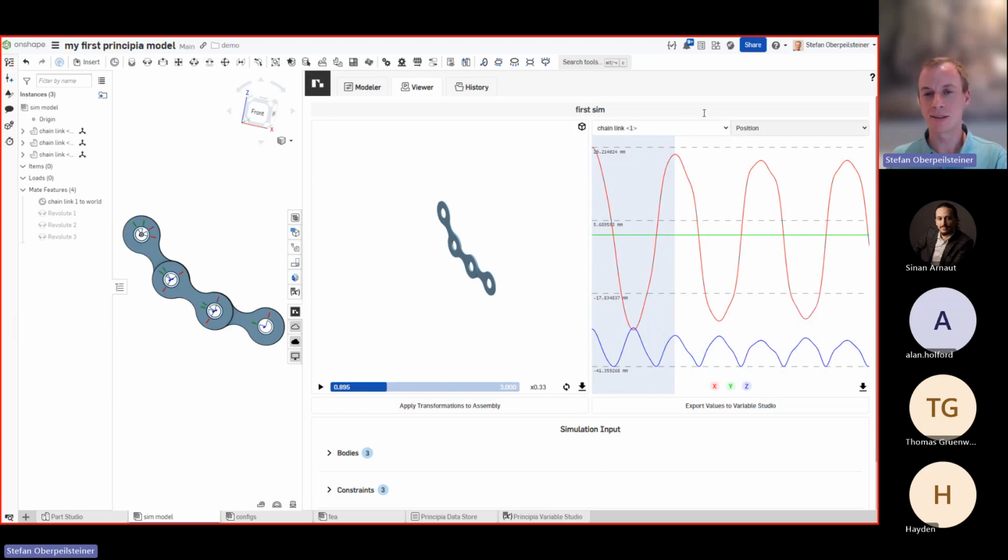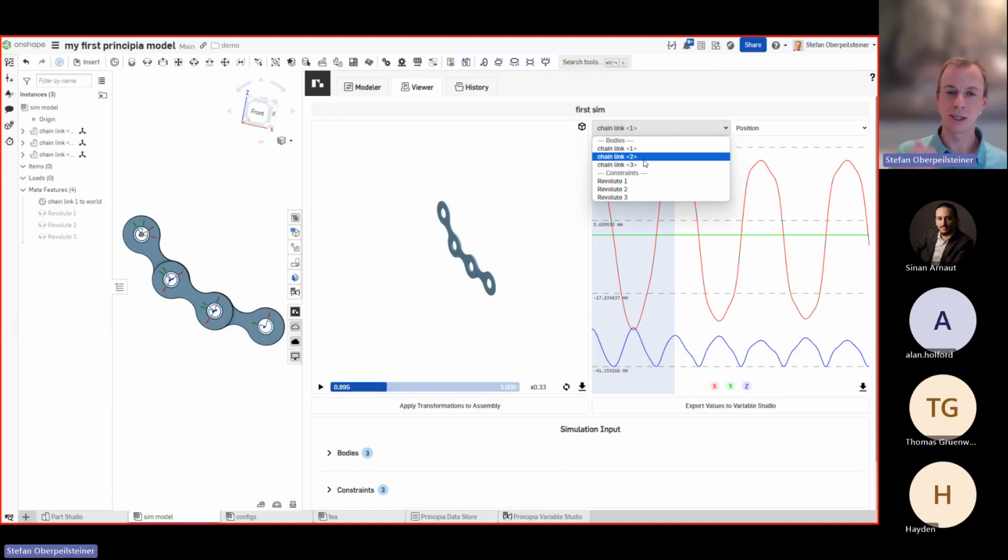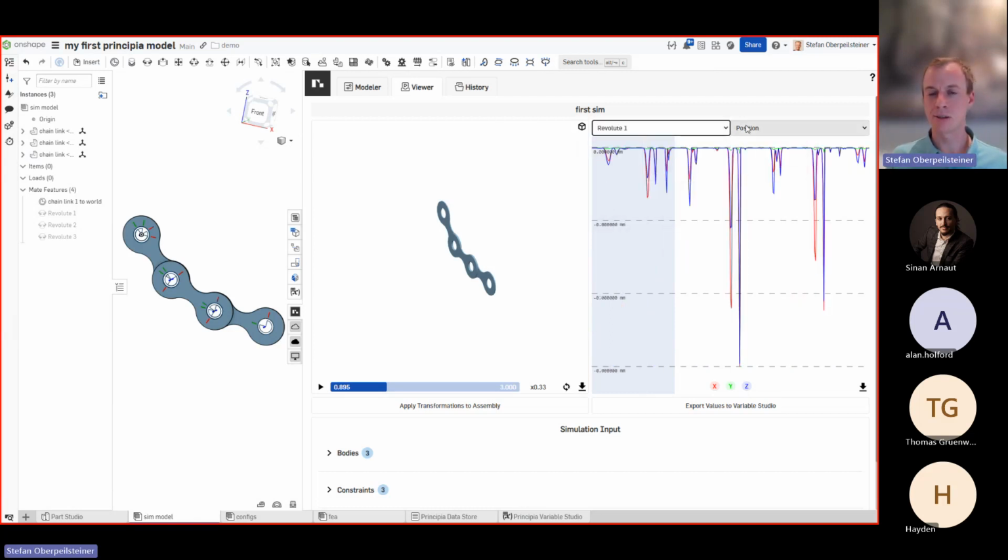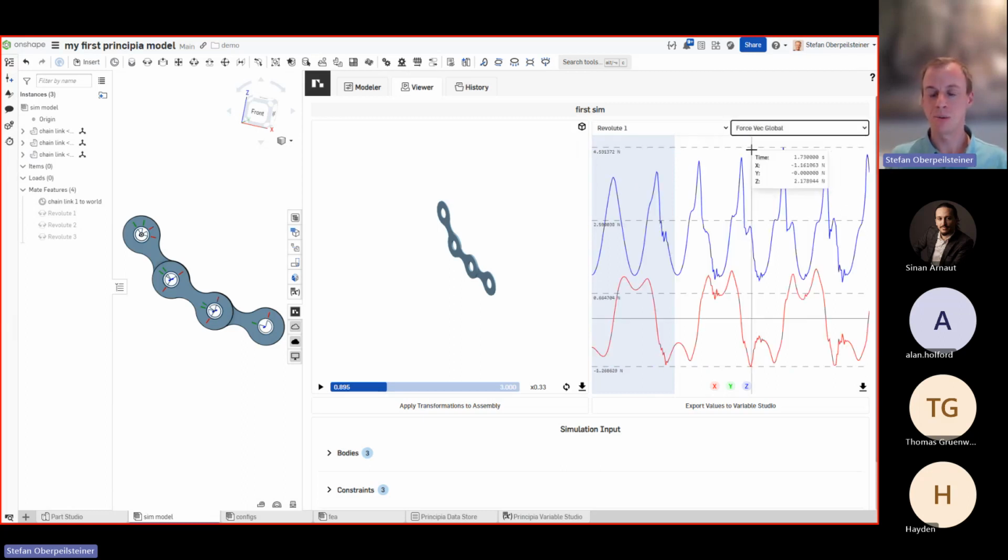On the right-hand side, you see the XY plot. And in the XY plot, we can really dive into the model in full depth. That means we can plot all the positions and orientations of bodies. Then we can post-process the constraints. That means where they are located over time, their position, and what about the forces between bodies in those constraint positions.